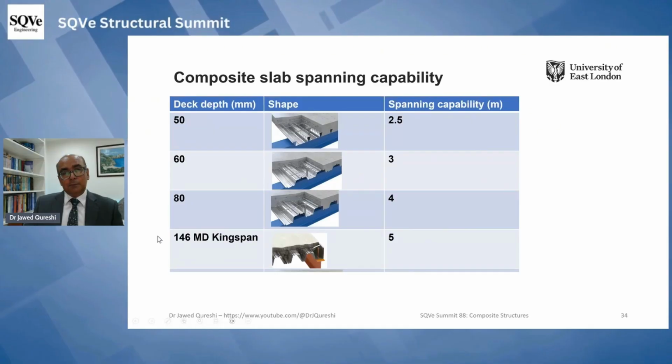And if you work out the shear stud connection, the strength of the shear stud using this decking, using the Eurocode formula, you will get wrong results. That will not be realistic. So this is a knowledge gap that needs to be filled.